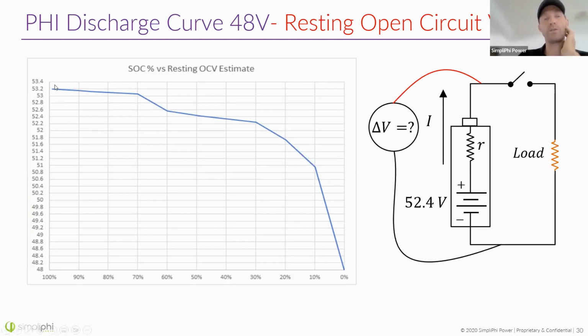So let's suppose the battery was discharging and you'll see the voltage start to drop. If the battery discharges by about 40% down to a 60% state of charge, that voltage will drop down from about 53.2 by a little over half a volt to somewhere around 52.5. And that's the voltage you would see if you turned off the loads briefly. But if the loads are run, you would actually see a lower voltage than this. And so I'm going to try to explain that.